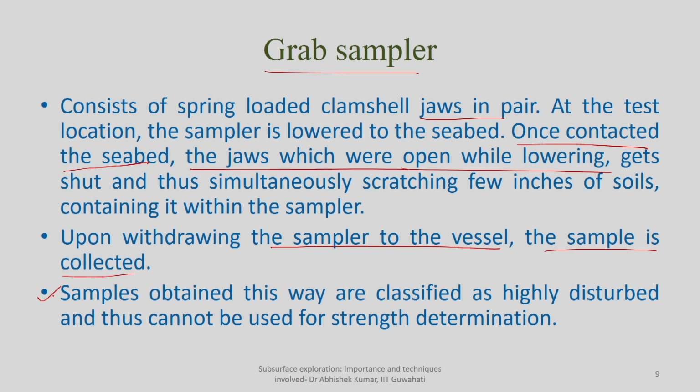However, one important thing here is that samples obtained in this way are classified as highly disturbed, because you yourself can understand, while collecting the sample, it is scratching, inducing some kind of external disturbance. As a result, the samples collected from a grab sampler are highly disturbed in nature, and you cannot use them for determination of the strength characteristics.